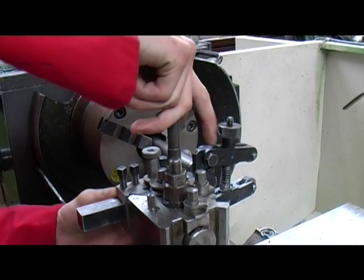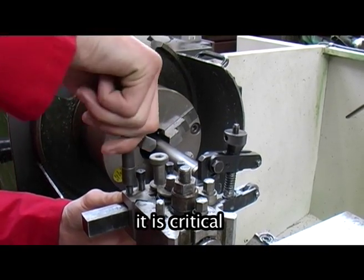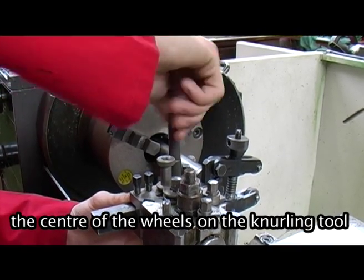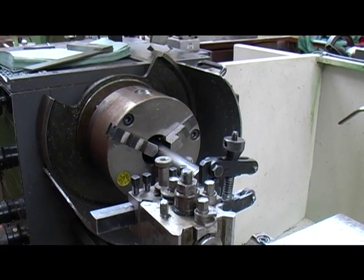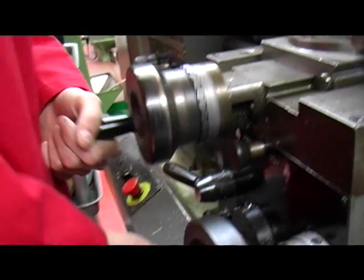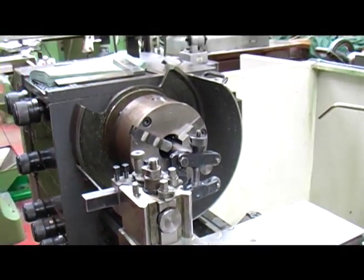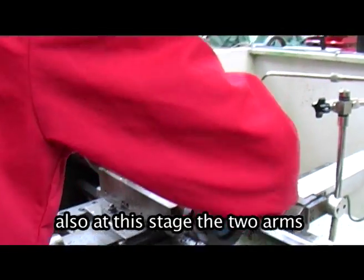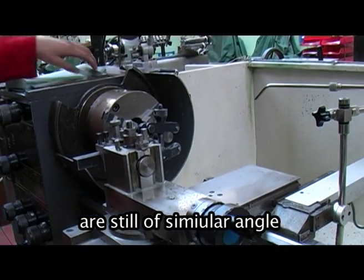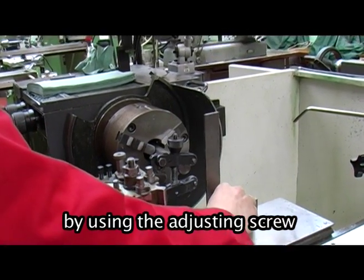Step 3, using the adjustment screw and an engineer's square, it is critical to line up the centre of the wheels on the knurling tool and the centre line of the workpiece. Also at this stage, the 2 arms, both the top and bottom arms, must be of similar angle, and again this can be adjusted using your adjusting screw.